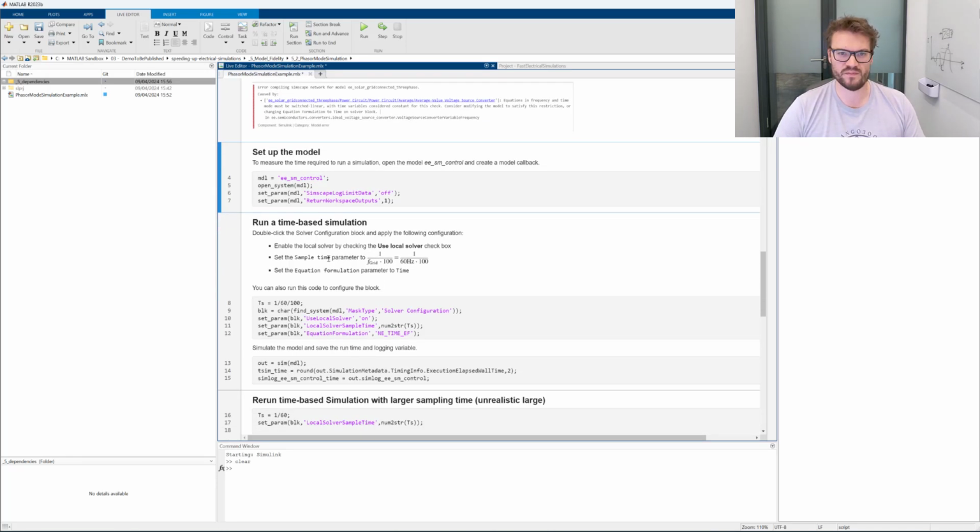First of all, before we speak about any ways to make a simulation faster by reducing the accuracy where not relevant, we need to make sure we have a high fidelity representation of the simulation saved. So as base case, let's use, as said, the rule of thumb of 100 samples per period. So we can set our local solver to this resolution.